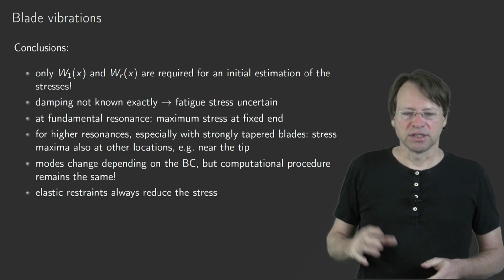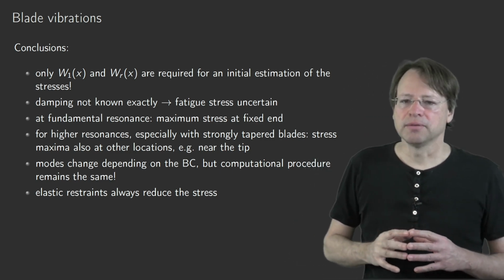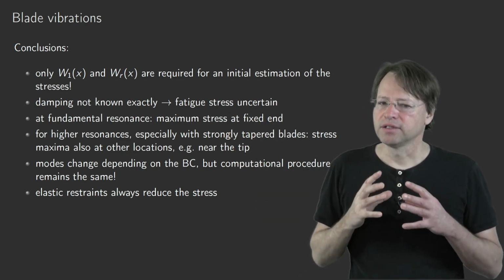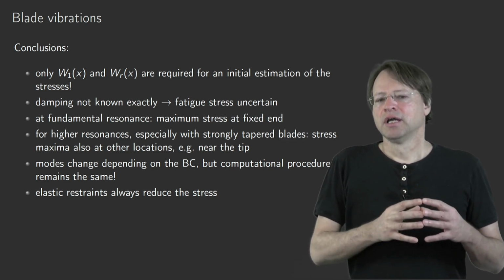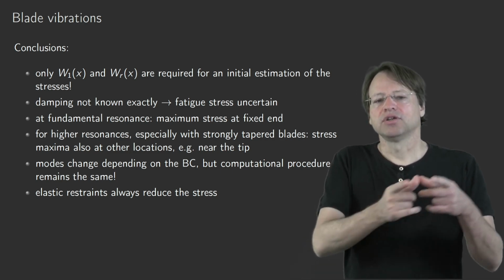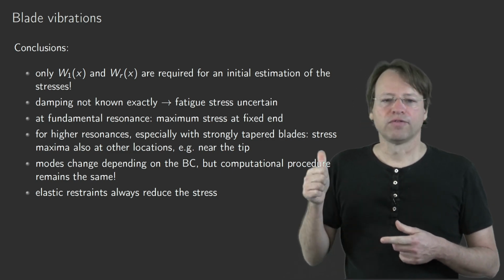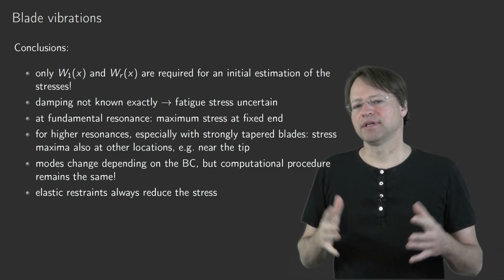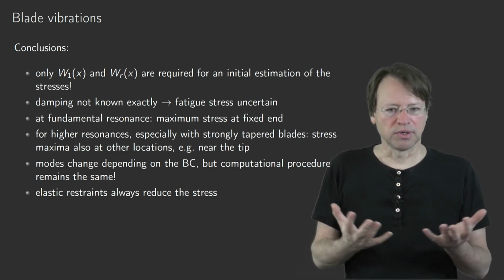So what you saw is a nice scheme, the Galerkin scheme. That's not only applied here for these blades, but the hidden story is that this is a typical numerical approximation scheme to transfer partial differential equations into ordinary differential equations to make use of, well, what you have obtained from the homogeneous solution, namely a nice set of mode shapes that is problem specific.